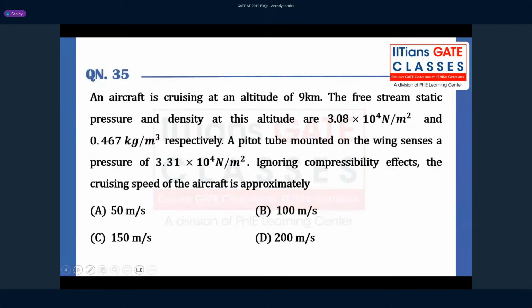Let's do this quickly. So it says an aircraft is cruising at an altitude of 9 kilometers. The free stream static pressure and density. So they have given you P infinity, they have given you rho infinity. Okay, static pressure, static density. A Pitot tube mounted on the wing senses a pressure of 3.3 into 10 power 4 Newton per meter square, right? Ignoring compressibility effects, the cruising speed of the aircraft is approximately. So you have to find the speed, the airspeed of the aircraft, from the pressure and density data, right?